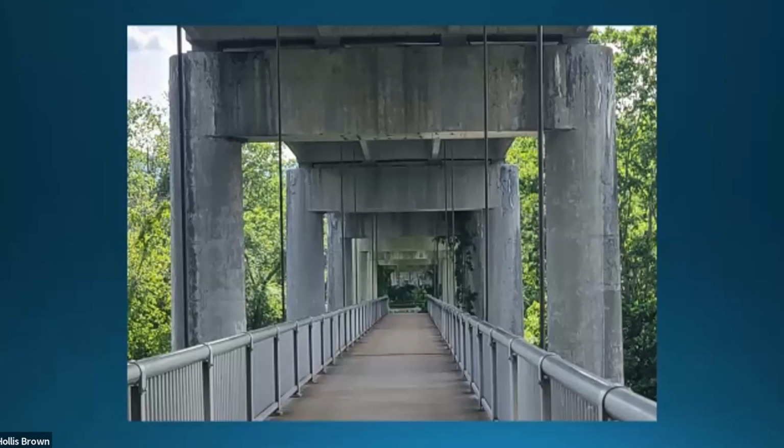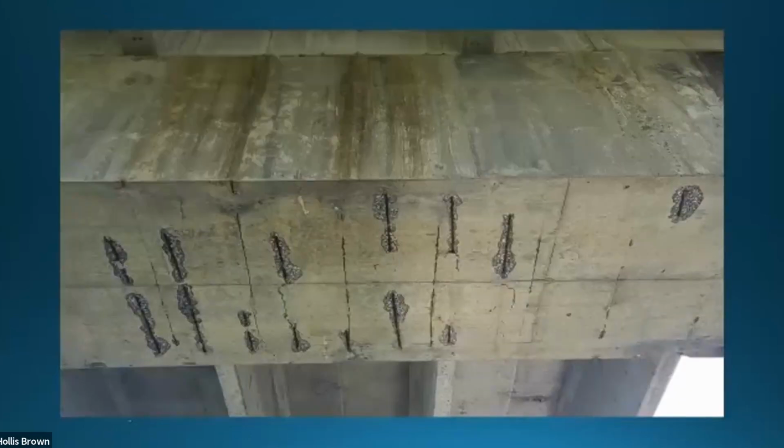But then here's a concrete with reinforcement. And what do you think caused this? It's steel rusting, but there's really a couple of things going on here. Number one, it's too close, which I think it's probably wrong to even minimize it to 1.5 inches. They were saying that reinforcement should never be closer to the surface of the concrete than 1.5 inches. I think it should probably be back further than that.